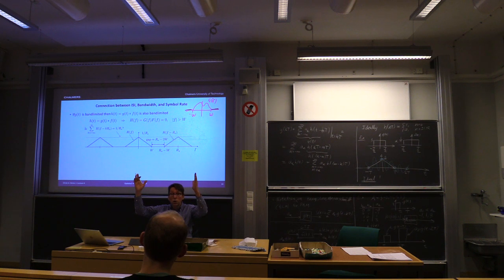Now, as long as there is a non-zero gap, we would never ever be able to achieve a constant value in the gap, right? As long as there is a gap here, we can never add something together. We can't add 0 together to get something which is non-zero. So as long as the gap is non-zero, we're screwed. There is no way we can do this, and there will be no Nyquist pulse. You see the logic? I hope?